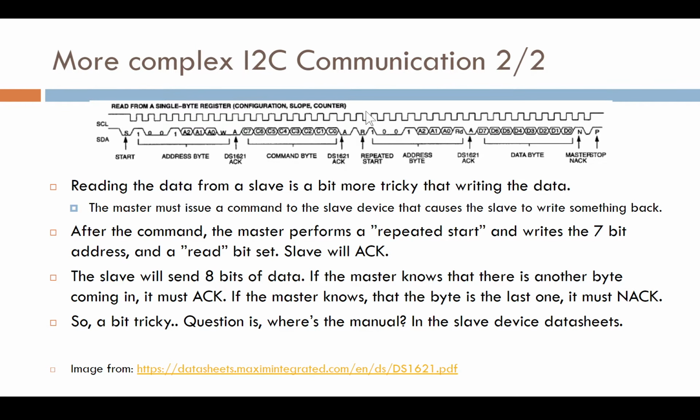When the clock is high here, small details here, I don't know if you can see it or not. When the clock cycle is high, you actually lower this data line. So release it there and then lower it during the clock high cycle. So it's basically a repeated start. So it immediately starts the next transmission, which always starts with the address byte, and now we have the read condition.